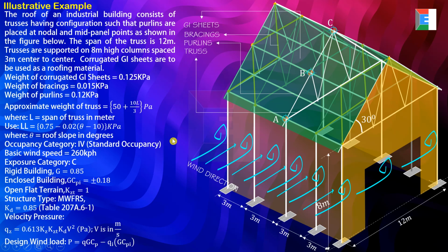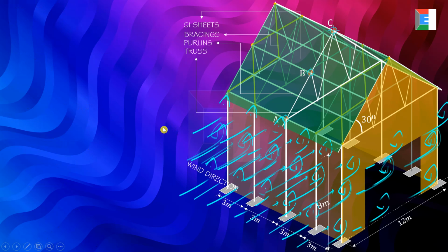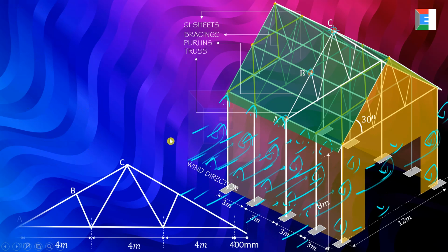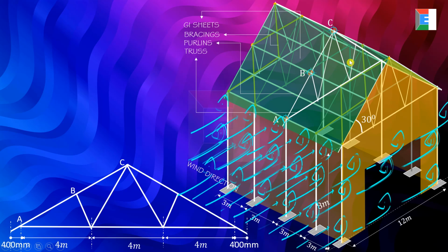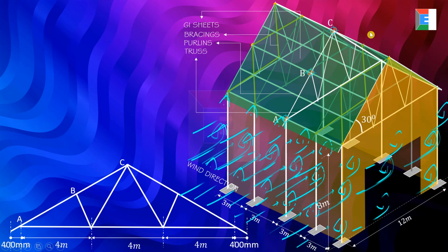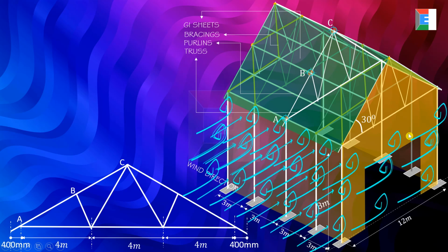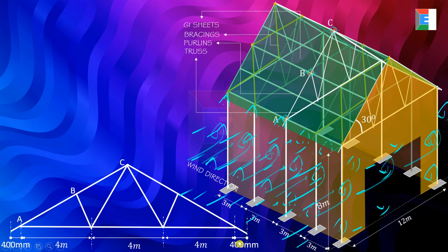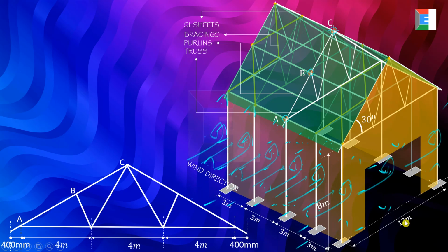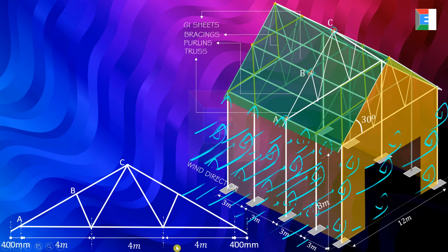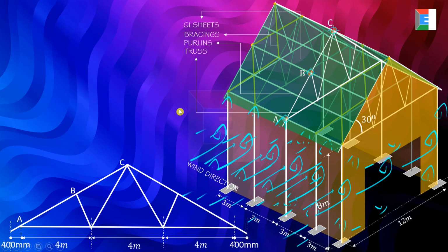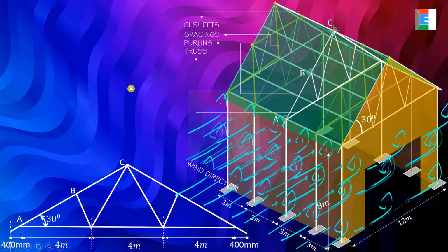So, yung details nung roof truss natin, kasi yung dulo nito is i-analyze natin yung roof truss. So, considering the gravity loads, yung dead load tsaka live load, and itong wind loads. So, meron siyang 400 mm dito, 400 mm, and then at L over 3. No? So, kung meron kang span na 12 meters divided by 3, so 4 meters, 4 meters, 4 meters. So first, we need to compute yung gravity loads.